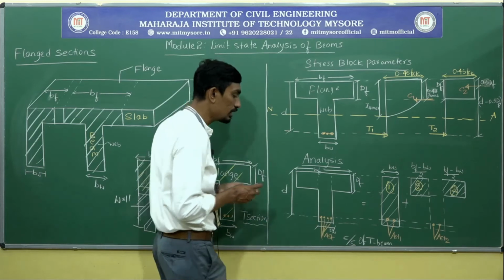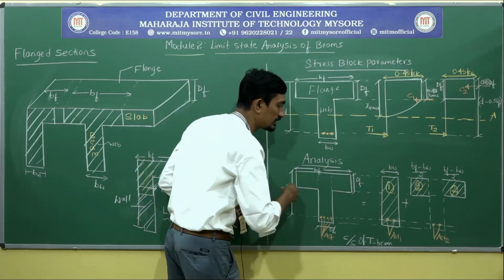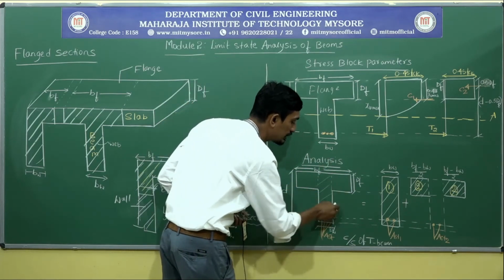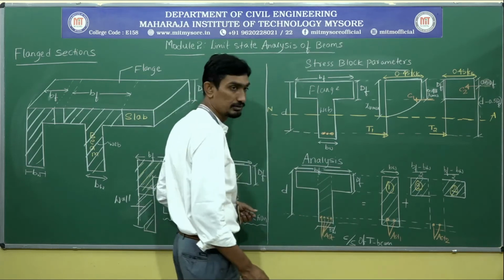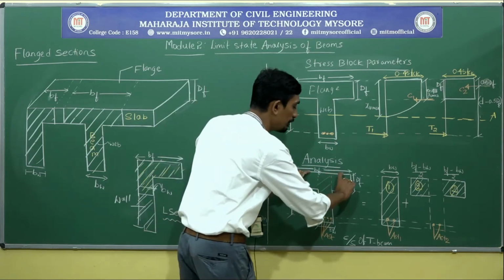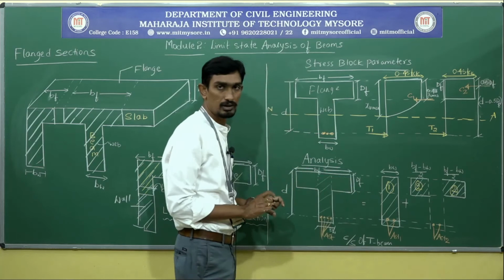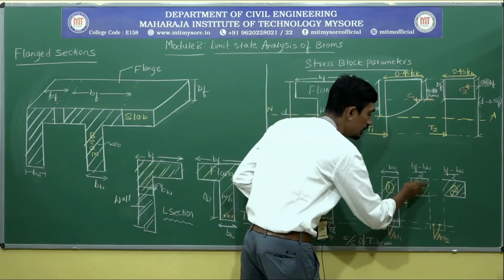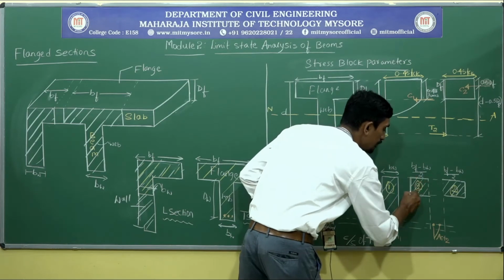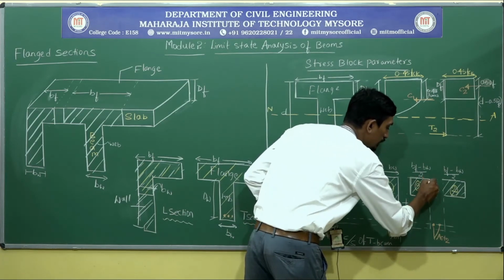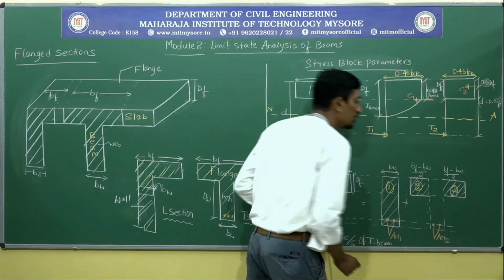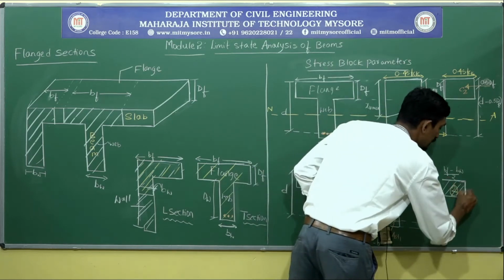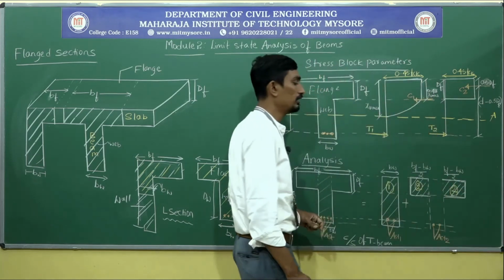Next, in this overall T section, deduct this portion. The left out portion will be two rectangular boxes. Two rectangular portions, that is what I am going to represent. So this will be your rectangular box, and this will be the semi-solid line, that is not visible.